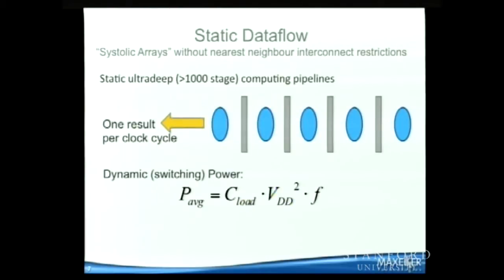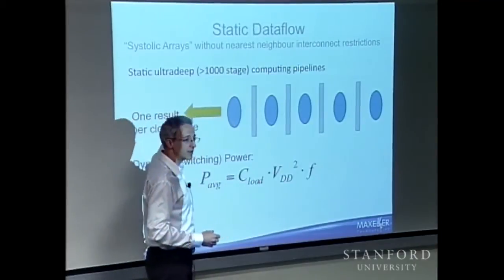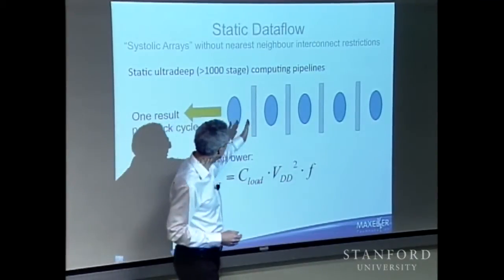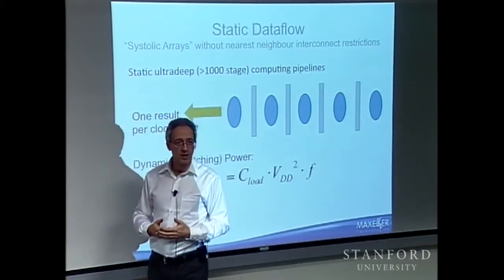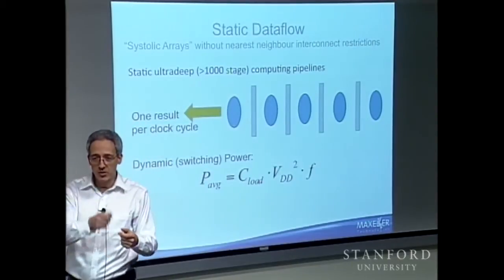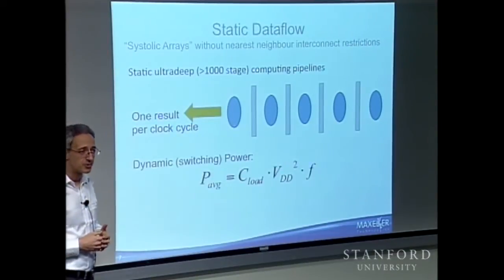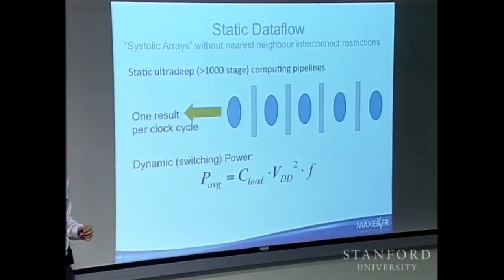Well, you need to stream the data in here at 1 gigabyte per second, and you stream it out here at 1 gigabyte per second, right? And so the clock frequency for this, the minimal clock frequency that you can use is the data rate, right? You need a tick of the clock to get the result out. Otherwise, it's not going to be easy to manage. You could get more, but then you're having signals floating on the wires, and that's all very, very inconvenient.